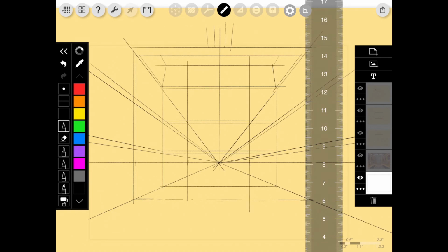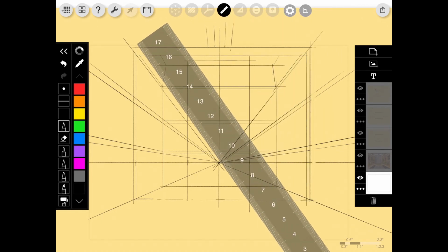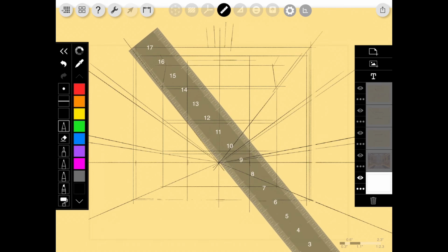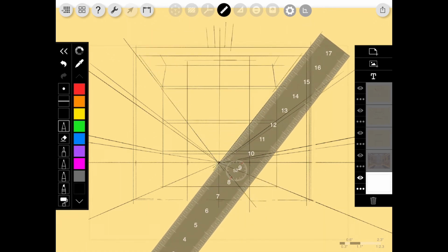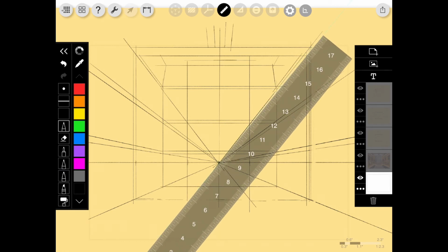We have this line at the bottom, which is the line that connects the two columns. So we'll use that as a reference to know where the cylinder ends. We know that is the middle of the cylinder. At the top, the picture tells us that the cylinder ends somewhere there. So let's project the edges. Let's project these intersections to the vanishing point, and I'll tell you why.